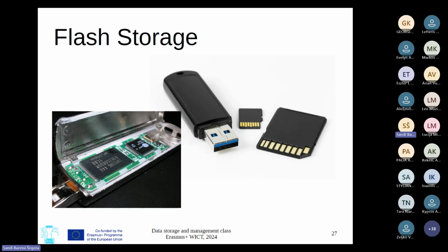They aren't without their issues. Writing and rewriting cycles, due to how everything is set up physically in flash storage, can destroy the storage itself. So they have a limited lifespan, a limited amount of read-write cycles that you can do to them.